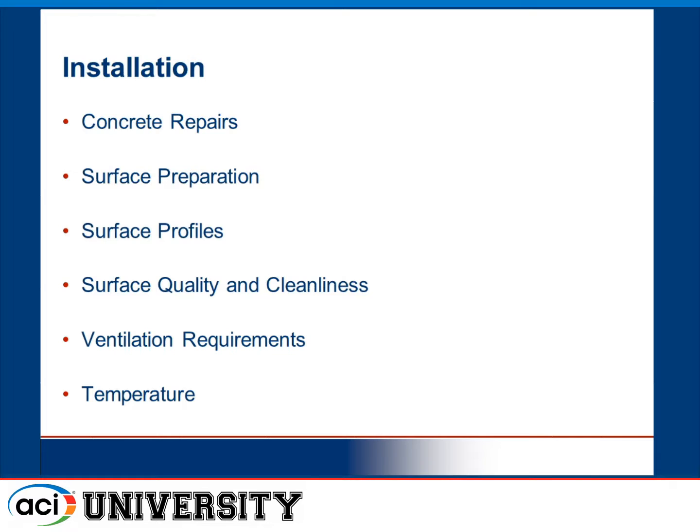Surface preparation may require grit blasting of the surface, and of course for that you need to have the concrete hard enough so that you can actually perform this surface prep by grit blasting. Surface profiles are important. The adhesion of these coatings depends much on the type of surface profile you have on the concrete base. And so cleanliness is very important. The quality of the surface is very important to ensure there's proper bond between the overlay and the concrete itself.